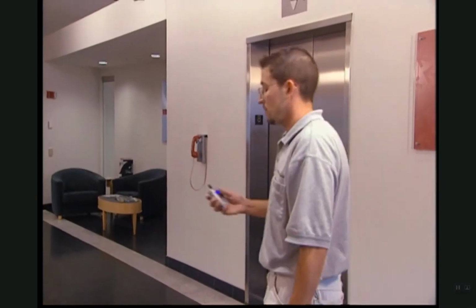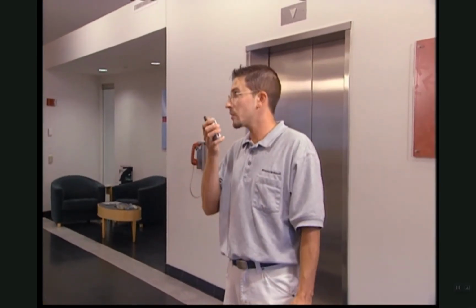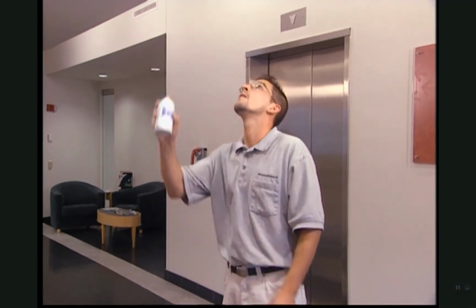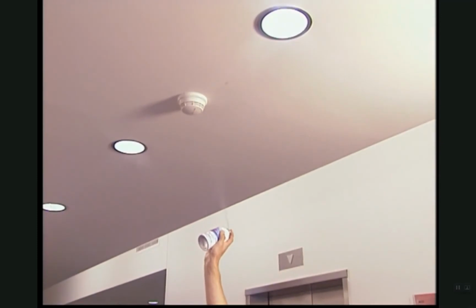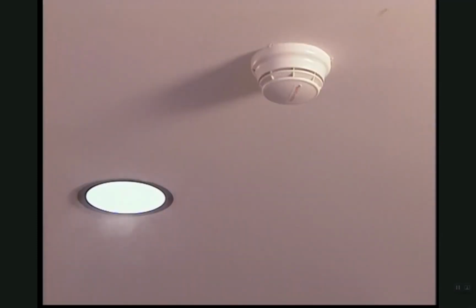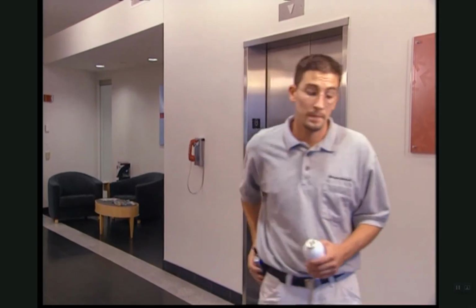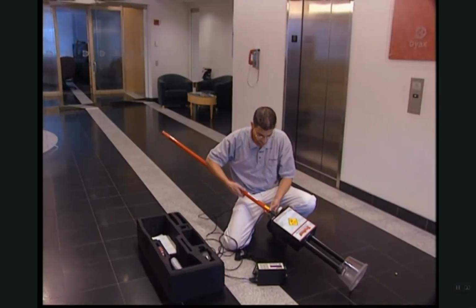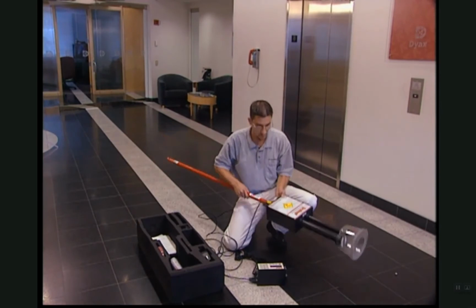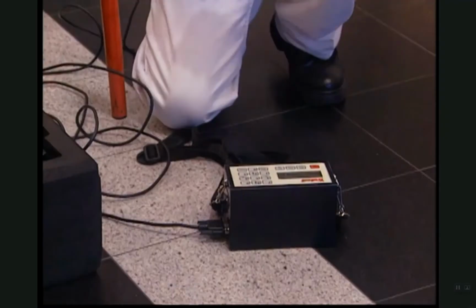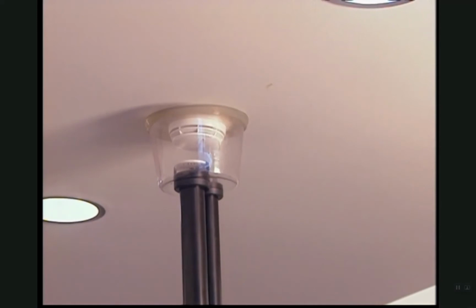Smoke detectors require 2 different tests. The first involves using smoke or a manufacturer-approved aerosol to activate the detector. Using a test button or magnet does not meet the requirements of NFPA 72, because part of the test is to confirm that smoke enters the detector chamber. The second test is a sensitivity test to verify that each detector is within its marked and listed sensitivity range. These are required at different intervals, depending on the detector. Check NFPA 72 for details.